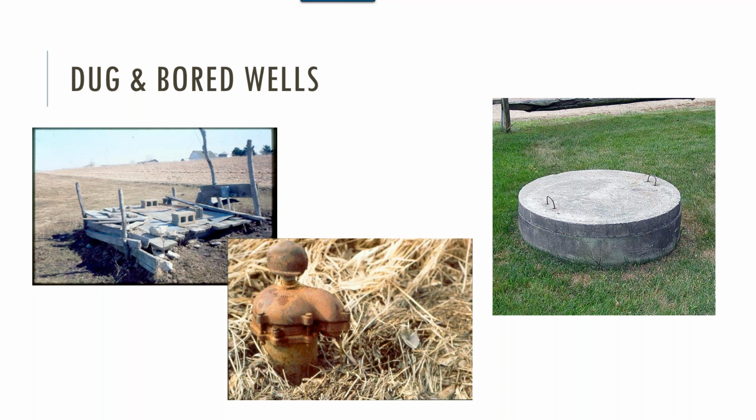One has the concrete tile, the one on the right, going all the way up to the surface. So it's 3 or 4 foot diameter all the way up. And the other one uses a standpipe and basically the wide part, the large diameter part of the well, and that concrete lid start at 10 feet below land surface. And that's preferred today for construction, just because then you can add a more clay earth material or earth fill in the upper 10 feet.